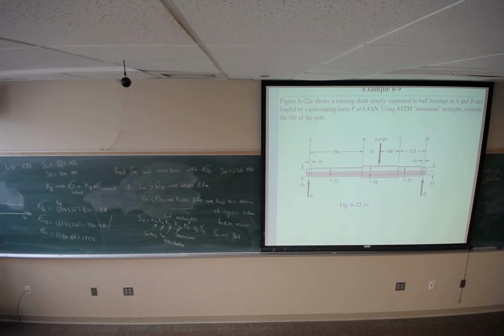So the stress that we have is going to be greater than SE. As you see, it's 330. So I will find this point, and then I decide which segment should be applied, either this one or this one. So this point is f S ultimate.